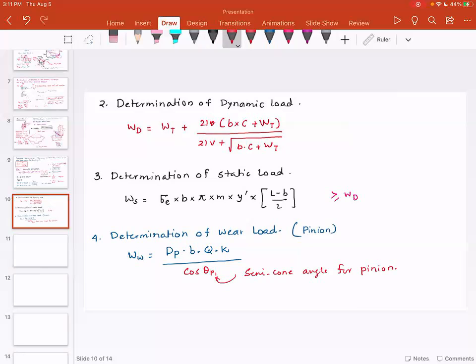And Q is equal to 2 times TEG divided by TEP plus TEG. So a word of caution, when we find Q here, we use formative number of teeth. In other words, we would use the equivalent number of teeth.